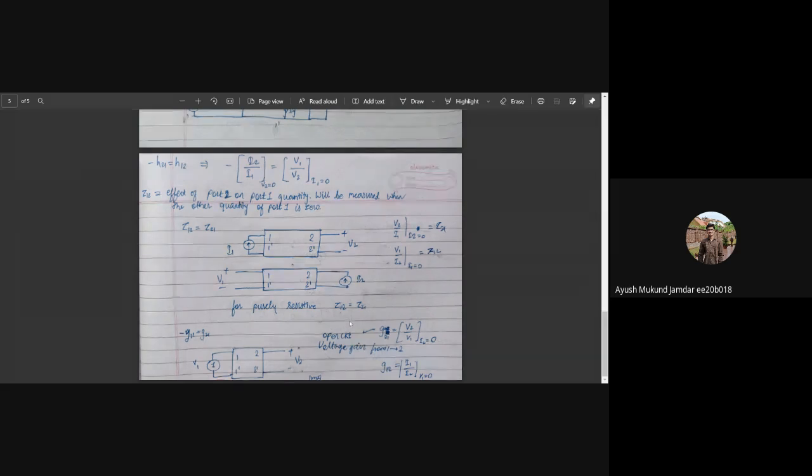So one might want to try out, if there is a problem that seems solvable by using the reciprocity theorem, starting with Z parameters and seeing if reciprocity works, later Y, H, and so on, finding the one which is the most simplifying parameter, applying that, and reducing the circuit to get the answer. Okay, so that's how two-port parameters work.